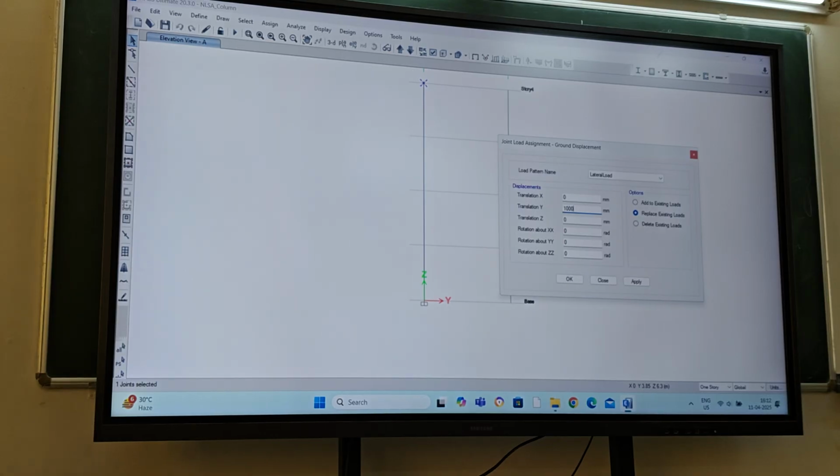It means the observation when you see the result, you can make some judgment. So that was my judgment. Initially, what happened? We applied the highest load. Then at the second stage itself, it shows the collapse prevention limit has been exceeded. So now, based on your understanding, you can give some judgment.